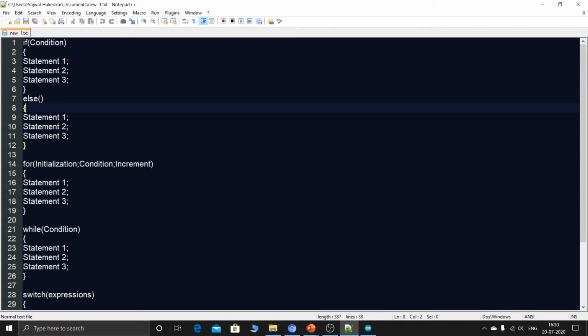Similarly, if I'm going to use a potentiometer, and it is just an example, okay, and if I'm using the analog read function, so I want a particular value and I want to turn on an LED after that particular value. Let's say the values are going to be between 0 to 1023. Okay, so I'll just say that I want to turn my LED on only when the value is above 500, and I don't want to turn my LED on until it is above 500. So for that particular application, I can go for this if else statement.